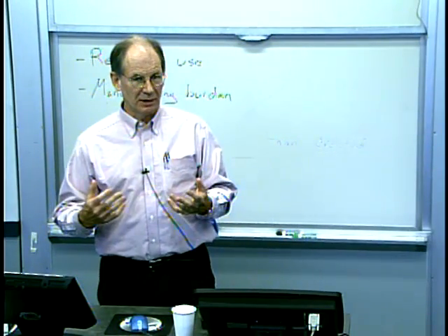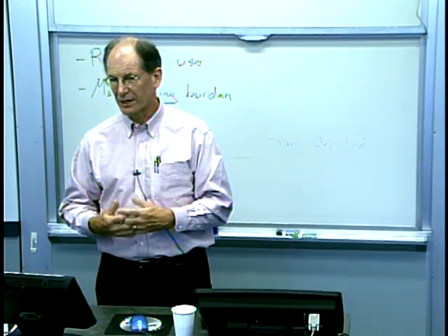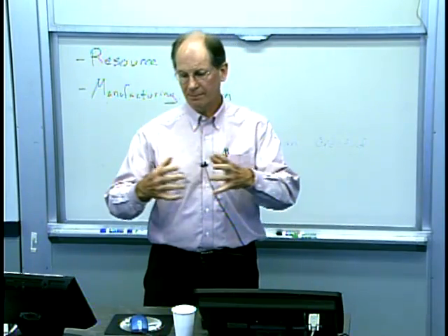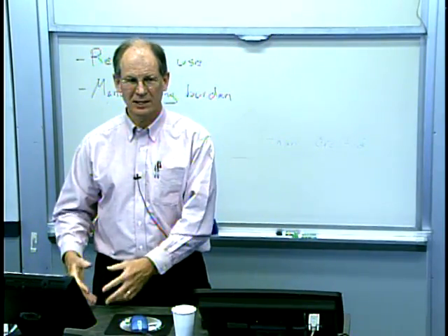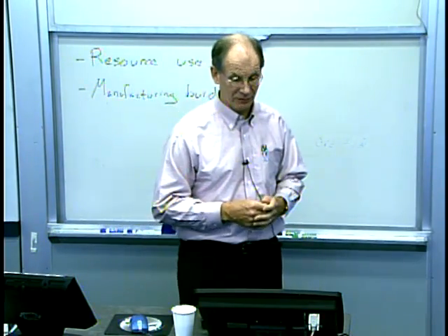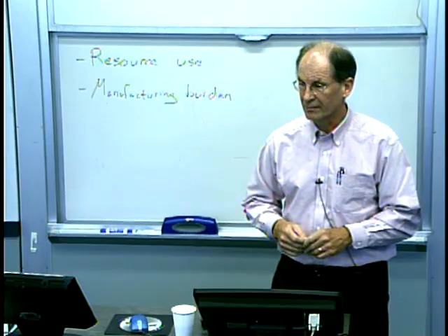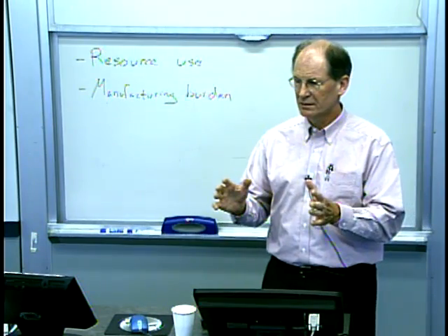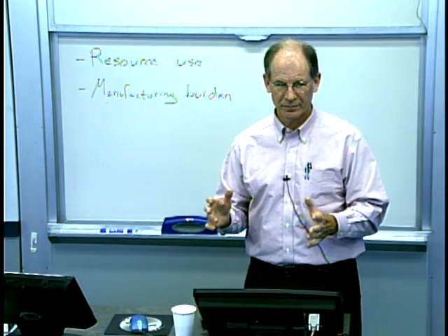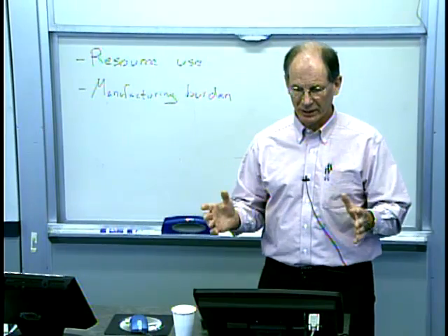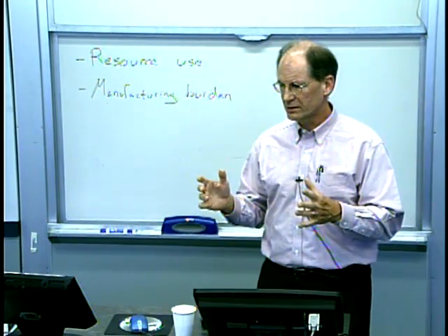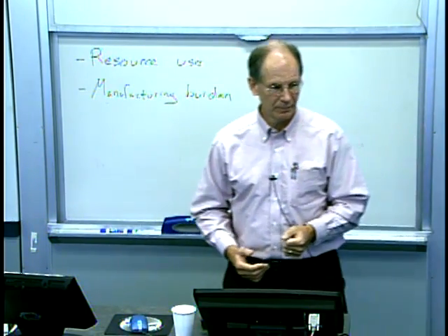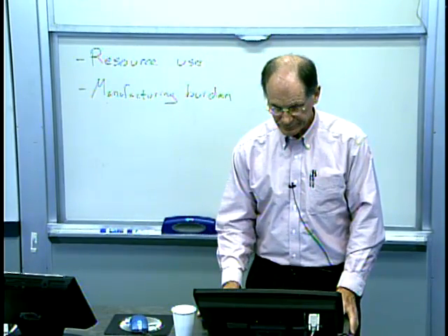And those are things that are related to the physics of the process that we've been talking about so far. And once that's done, what is the underlying statistical behavior, random behavior of the process, and how well can I characterize that? And SPC all gets down to really basically saying, have I achieved this state of pure randomness? Another way of looking at the Shewhart hypothesis is, if the process is acting in any way except purely random, then you haven't done your job. Then you can still improve the process. Okay?